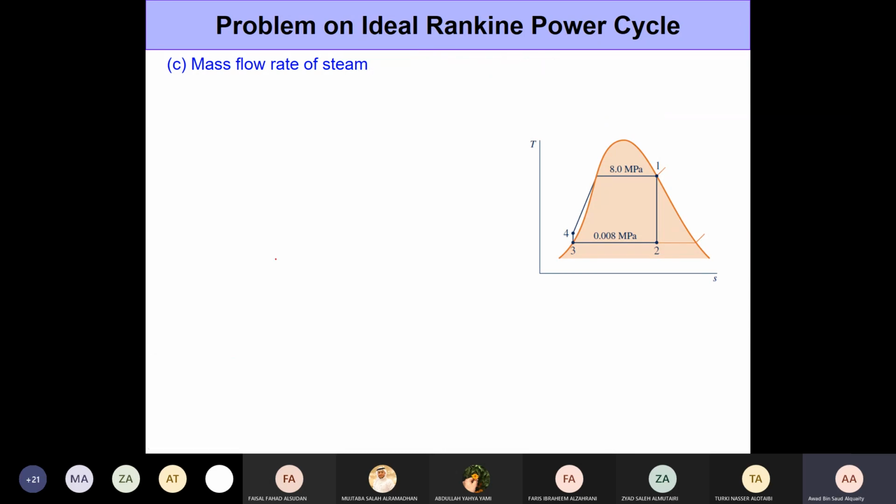All right, let's try to focus here, because your preparation is not going to change in the next 20 minutes. So we just need to get the mass flow rate. The turbine work output per unit mass is simply the difference in the enthalpies, which we already calculated. Same way with the pump.